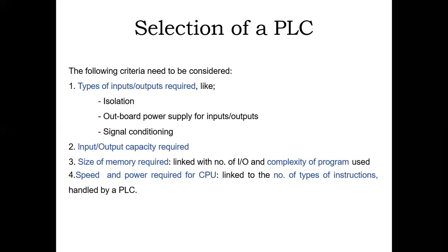Then the size of the memory required, which is linked with the number of inputs and outputs and the complexity of the program used. Memory is the main concept, because we are using different kinds of memory, ROM, RAM, and some registers. We need to define the size, because if we are using a large number of applications, we need to use different memories. Sometimes memory will be erased, so we need to use EEPROM. Then speed and power, this is the main concept.